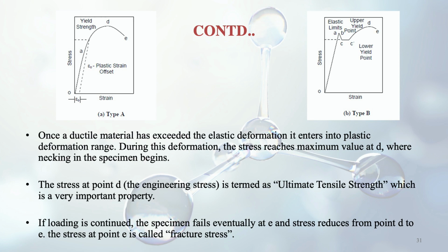But still it has not broken. Now the stress will come down. If loading is continued, the specimen fails eventually at E and stress reduces from point D to E. The stress at point E is called the fracture stress. So the point E is the point of fracture.